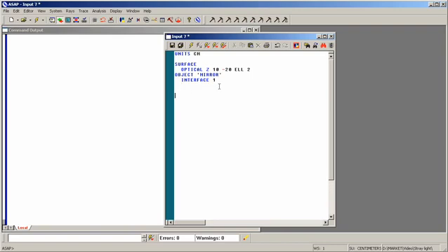Now we have to define a collimated source. Grid, elliptic, we'll place the source at z equals 0, give it a semi-diameter of 1, so we're going from -1 to 1 in x, -1 to 1 in y, and just for an example, we'll have a 25 by 25 grid of rays. We're going parallel to the z-axis, source direction, x component of 0, y component of 0, z component of 1. We're going to set up a window in the usual way.